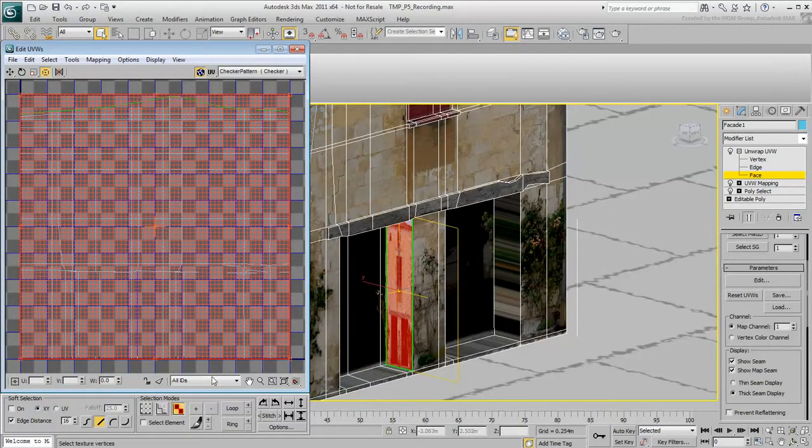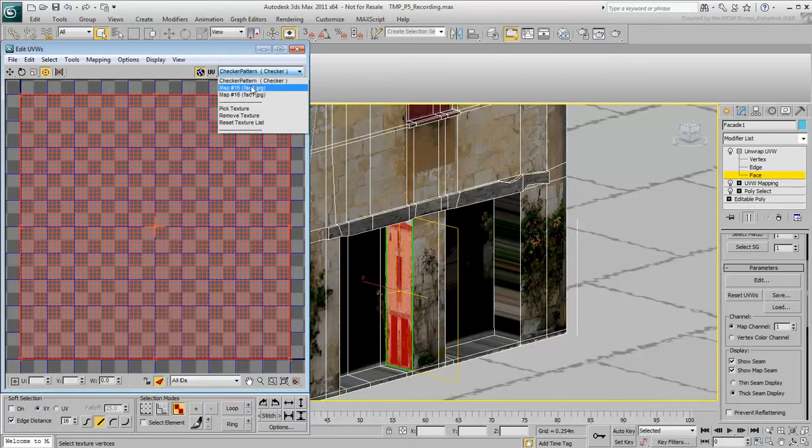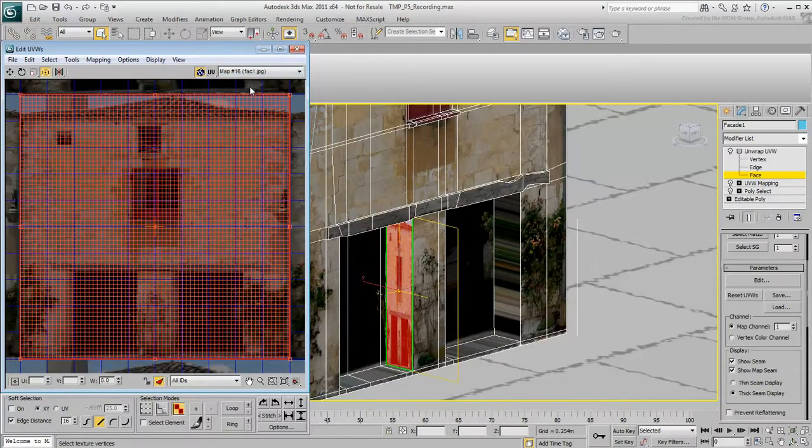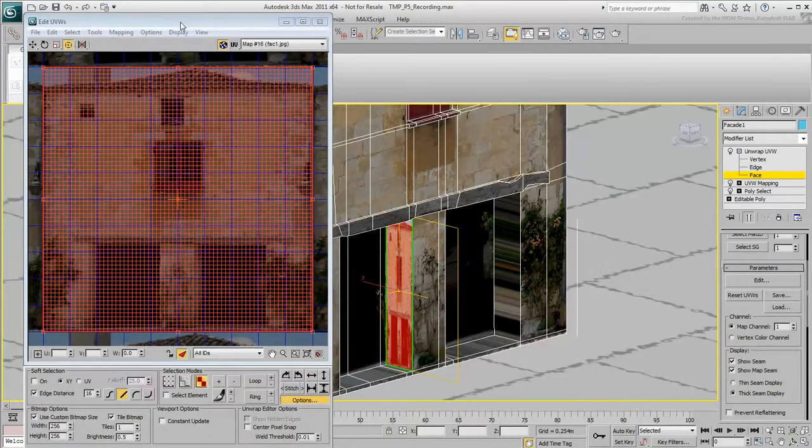Use the Filter mode to only view the selected faces. To make your work easier, you can display the building texture inside this dialog for reference. You can also set the option for brightness to be lighter, making the texture easier to read.